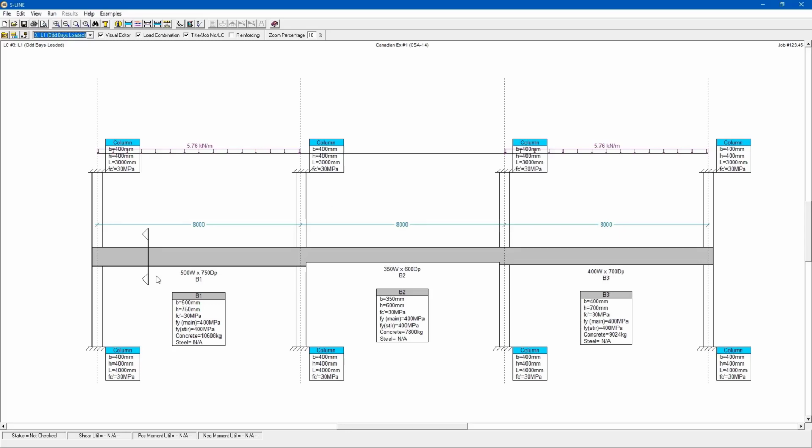So this is S-Line right here. It's used for concrete beam design and detailing, and it looks at the continuous length of a beam, so it considers things like stirrup spacing, bars, cutoffs, and whatnot. And it can have multiple bays with different section properties at each. However, for our example, we just have a simply supported 8 meter long bay, so I don't need to go into that much detail. So I'm going to change this.